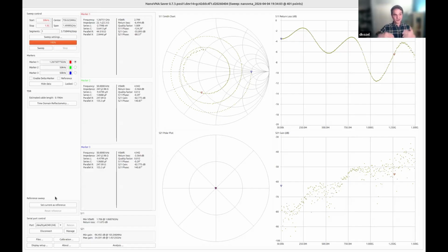If you're only measuring how much power is reflecting off an antenna, maybe that doesn't matter. But if you're trying to do something like measuring the matching network and you're going to be adjusting impedance, adjusting capacitance and inductance and stuff like that, you need to be recalibrating. So I have just completed the measurement. I'm going to put a 3 dB attenuator in between port 1 and port 2, and hopefully we'll get a nice clean trace. Well, actually, I'll leave it unconnected for the moment.